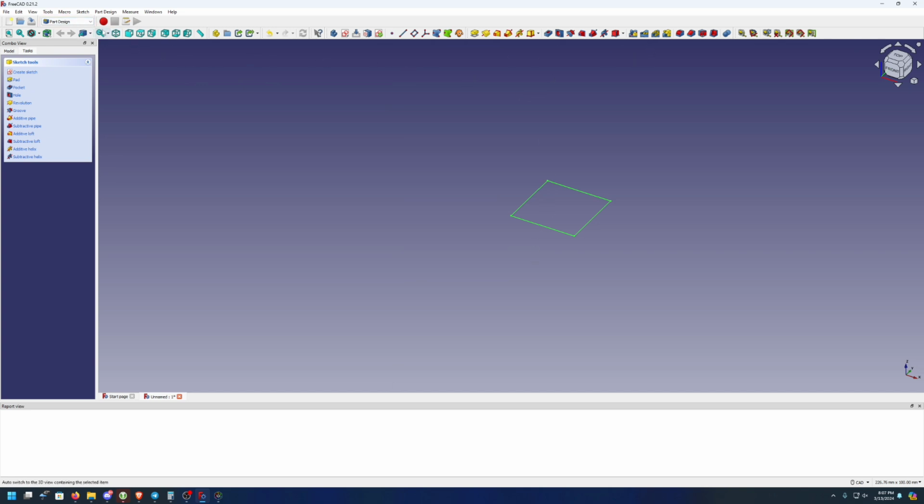And then here's the other toolbar, the Part Design, the other set of tools that you need to be familiar with. Of course these stay pretty similar. These are just create new sketch and all that, which leads you back into the sketch workbench. The 3D specific tools that I use the most are these. The most important 2 to remember are Pad, and I don't have tool tips. Okay, there we go. And Pocket.